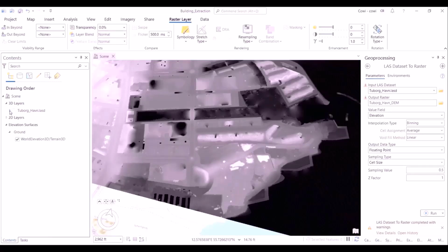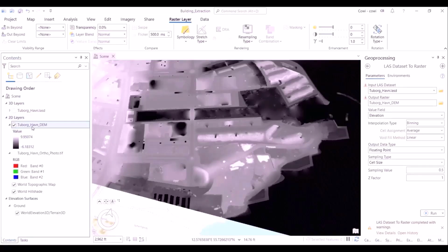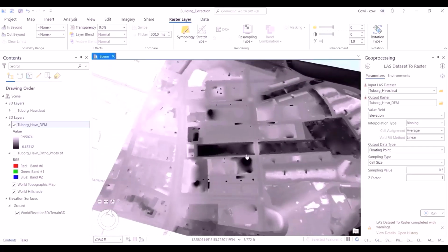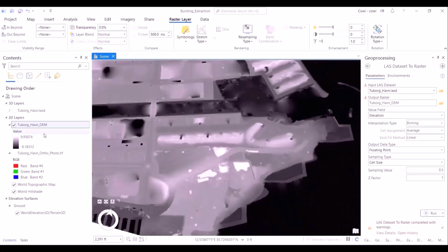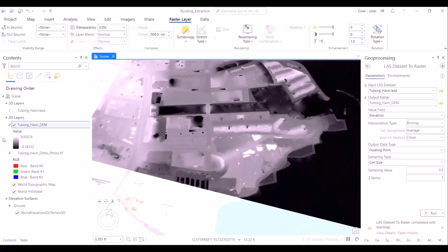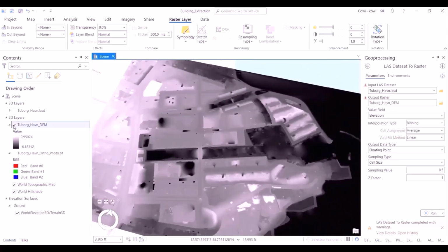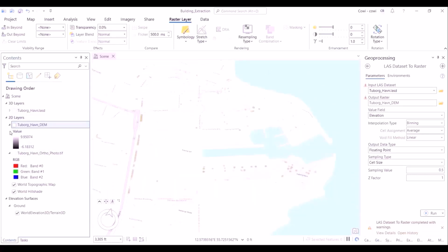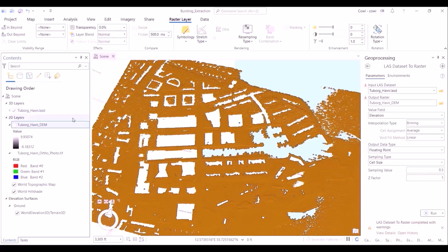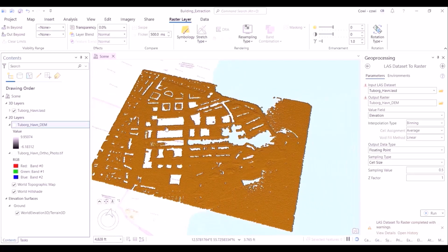So using the natural neighbor method, we've classified. The DEM has been created. Areas which are high are brighter in color, whereas the areas which are of low elevation are darker in shade. This forms the framework of our processing: the ground points converted into a DEM.